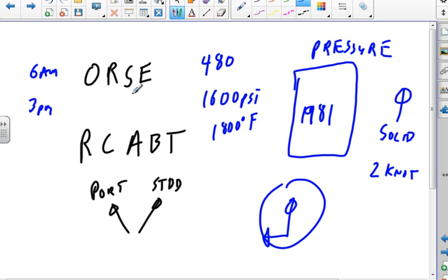Anyway, 2 days later, we find in the rotary switch, that's the compensated, uncompensated level for the pressurizer, we find a fault in the switch. A piece of wire embedded in the plastic that had been there for 20 years without causing a problem, that caused a problem for whatever reason the day before. Wow. Totally amazing. We could actually find the problem, and as soon as we found it, we replaced the switch and we got the level back. Everything was fine.